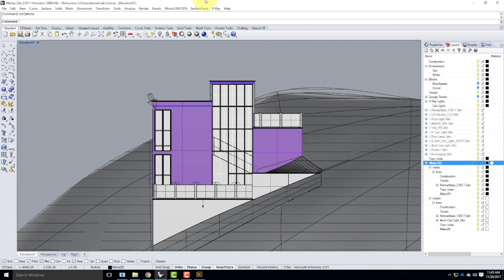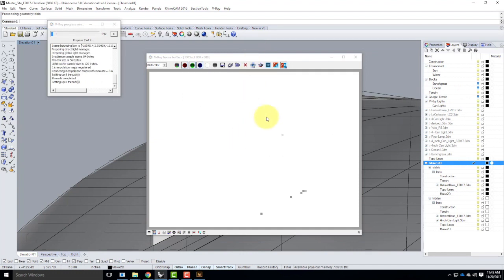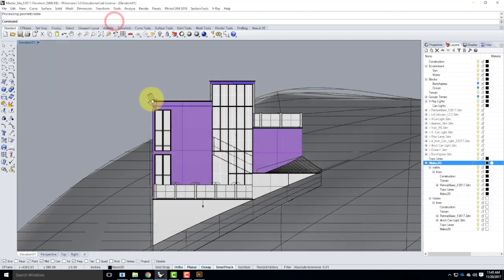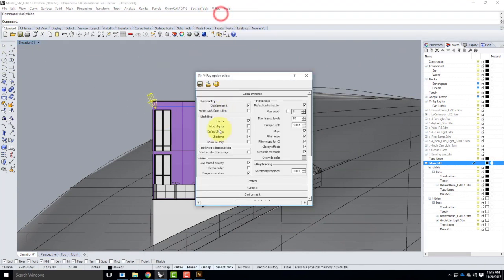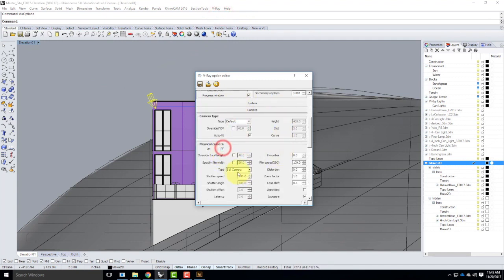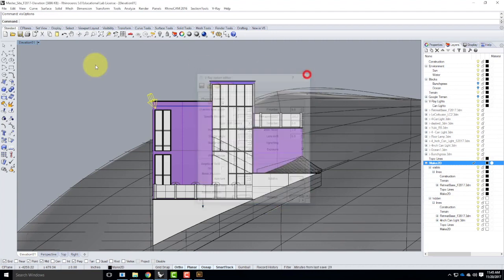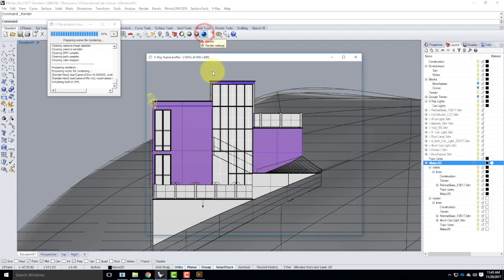And so at this point, we could go ahead and render and say, what does it look like? Well, it's significantly too bright because I still have my sun on. Now, I have two different options when it comes to adjusting for the sun. I can either go into my VRay Options, and I can go into my camera, and I could turn, well, that's weird. Let me turn the physical camera on. Should have been on. Clearly that setup isn't right.